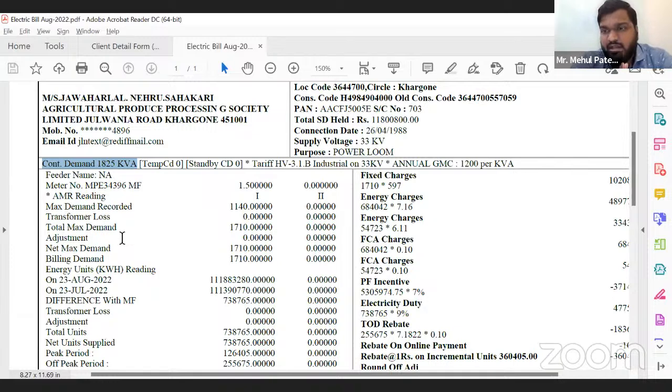Now, how is it important? How does it play a role in deciding the estimated solar PV capacity? It comes from the policy of the state. Each state has different policies. In Maharashtra, we have an office in Mumbai. The policy from MERC, the Maharashtra Energy Regulatory Commission, is that we can install up to 90% of the contract demand mentioned in the electricity bill as solar.